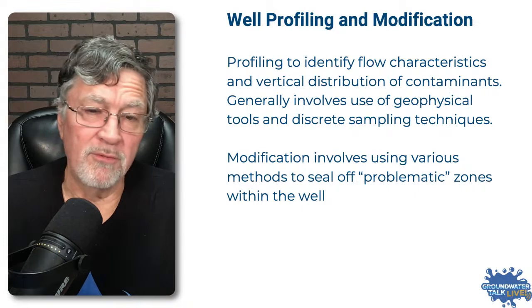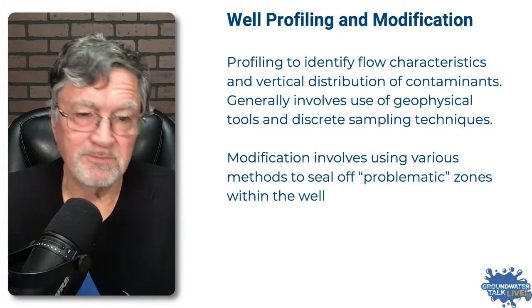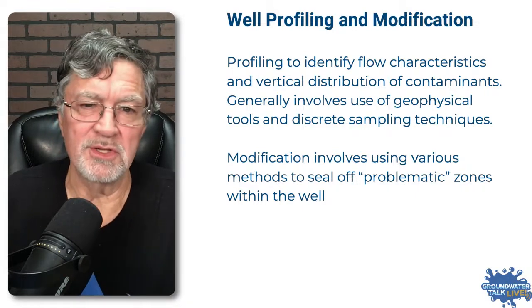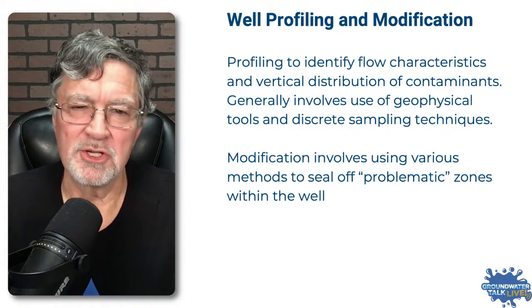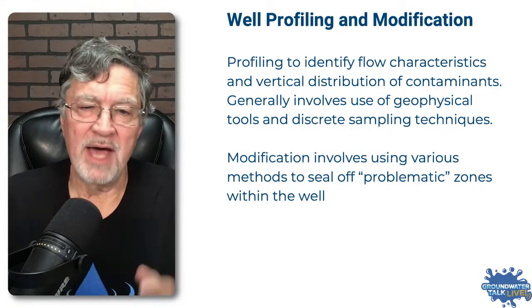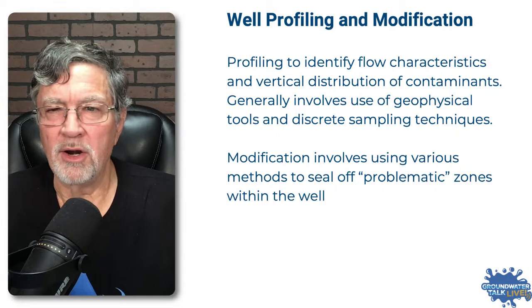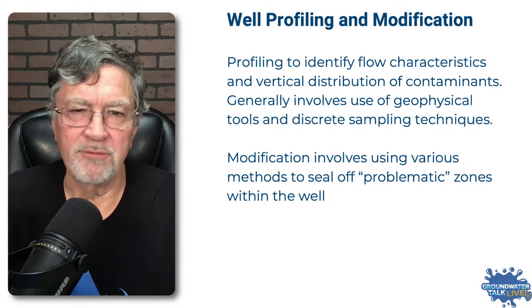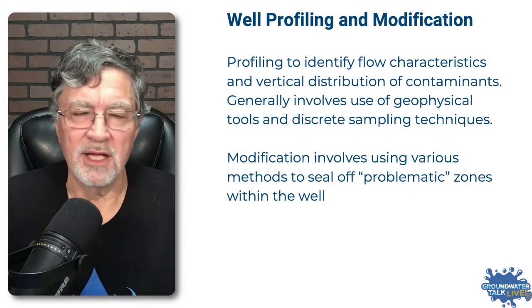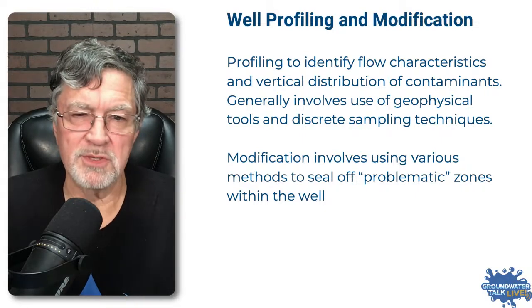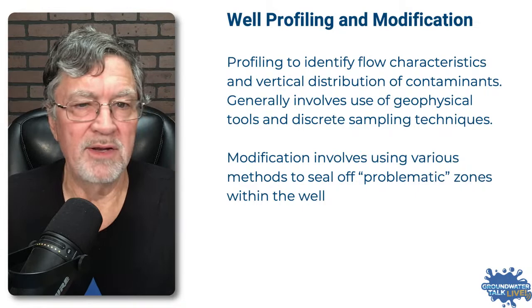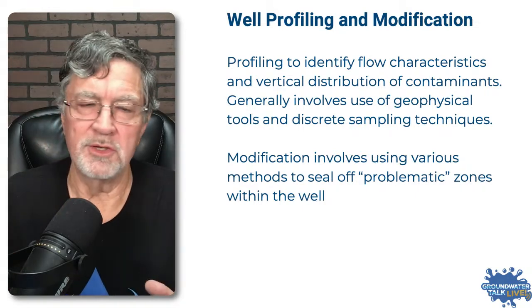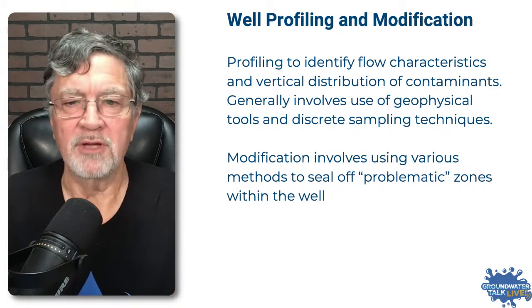We have done some of the profiling where we've gone in and looked at arsenic, for instance, and it was pretty evenly distributed throughout the well. That is not a situation where well modification can work. If you have well-defined zones that you can identify during your profiling process, then that is a situation that is just made for well modification.